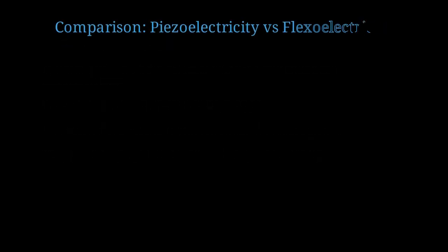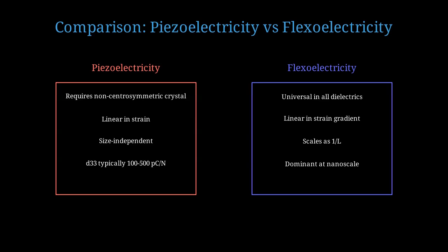Let's compare flexoelectricity with the more familiar piezoelectric effect to understand the differences. Piezoelectricity requires non-centrosymmetric crystals, is linear in strain and size independent. Flexoelectricity is universal, linear in strain gradient, and scales inversely with size, becoming dominant at the nanoscale.